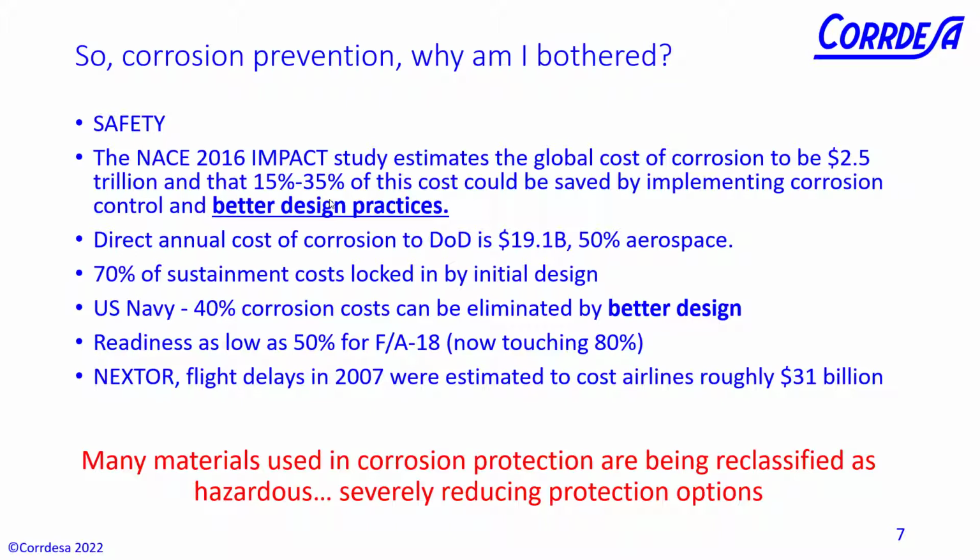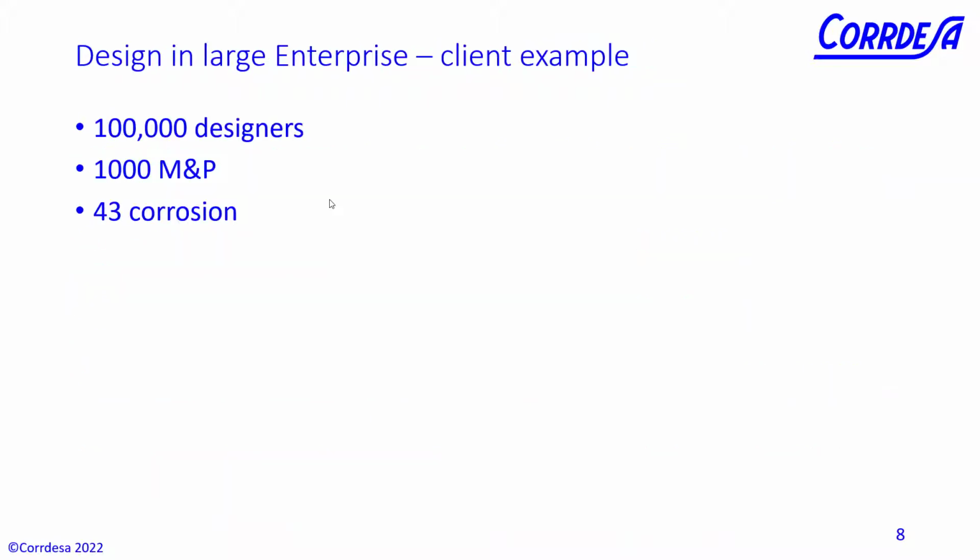You can choose some materials early on in your design, but when it comes to maintenance several years down the road, those materials can end up being banned. For instance, cadmium, an awesome product for corrosion protection, has now been eliminated, and zinc nickel is a replacement coating. So after decades and decades of experience with other systems such as cadmium, how can we suddenly implement and deploy a new coating in a matter of a handful of years? It's very challenging, and computational simulation can help that process.